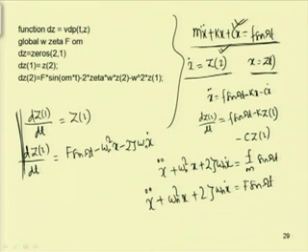So, by putting these as global variables, one can write dz equal to zeros. As we have two equations, we put zeros(2,1). So, dz1 equal to z2, this is the first equation, and the second equation is dz2 equal to f sin omega t minus 2 zeta omega z2 minus omega square z1.